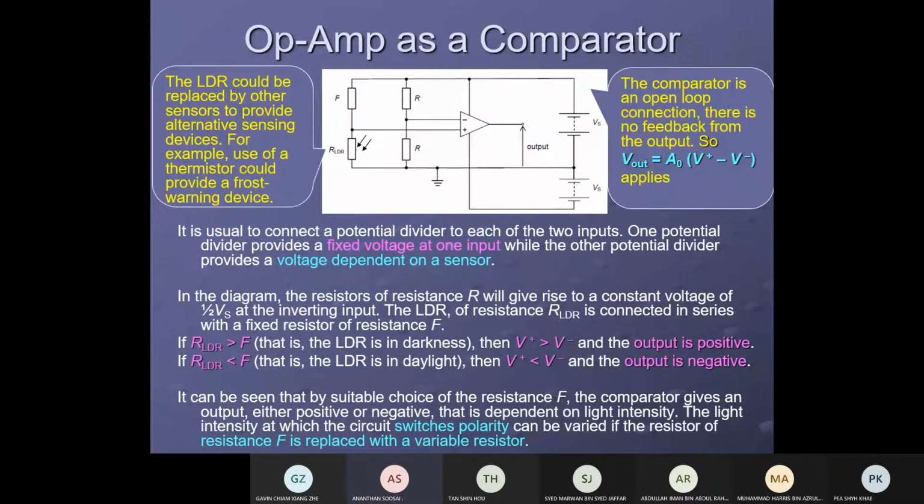Now I'm going to add more questions. Look at this. This LDR is used for a street light. Here, up is positive 10 volt, down is 0 volt. With equal resistors R, the potential difference, each will take 5 volt. So the voltage going to the negative input is the lower resistor's voltage, which is 5 volt.